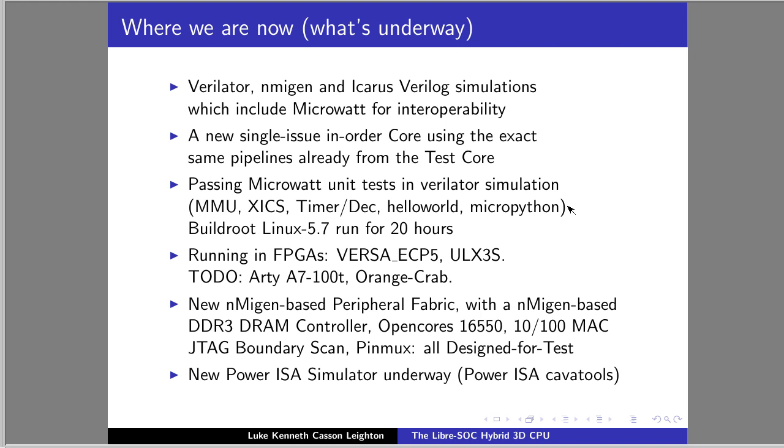And then you add, say, an Ethernet peripheral. You want an Ethernet peripheral, and well, now you've got two peripherals. You have your memory and you have Ethernet. Well, which one gets priority? So now you have to have an arbiter which splits the memory requests between the two, and so on and so forth.